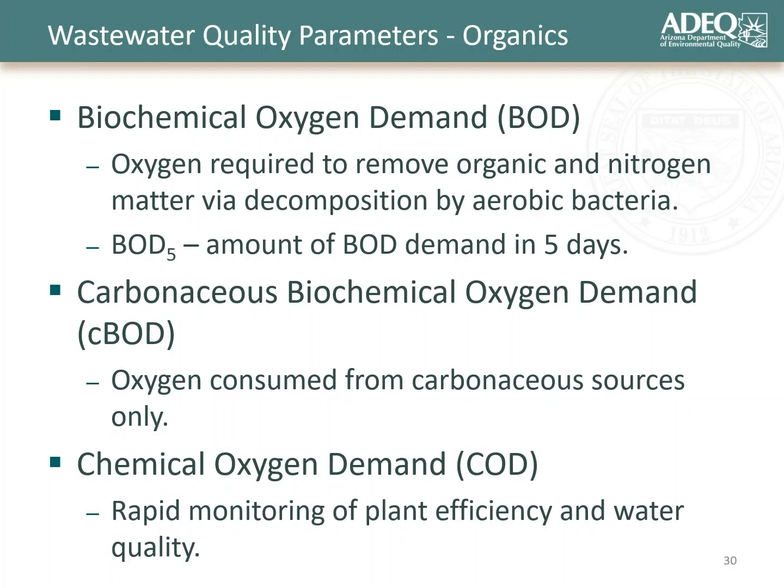So there are many different ways we can measure oxygen demand. There's BOD, CBOD, and COD. BOD, or biochemical oxygen demand, is the oxygen required to remove organic and nitrogen material by decomposition by aerobic bacteria, typically set in a 5-day increment.